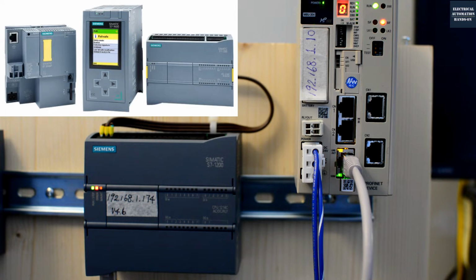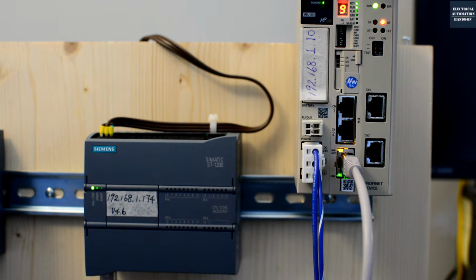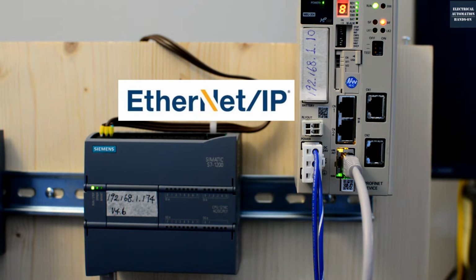And on the YASKAWA side, I'm using the MP3300iec. So we can implement the Siemens side running as the Ethernet/IP adapter function. And the MP3300 motion controller, using this built-in port, can run Ethernet/IP as a master. So we do not need to purchase additional hardware. We only use the built-in function of the MP3300 to communicate with the Siemens.